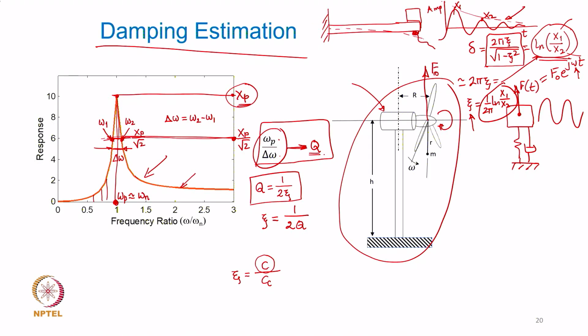The advantage here is that you can run that vibratory system at different frequencies, and mostly because they are run by an external controllable excitation source, you can actually run them at different speeds and get that response curve.